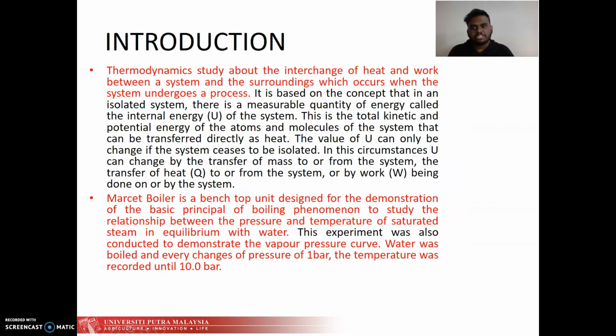For the next part, introduction. Thermodynamics studies the interchange of heat and work between a system and the surroundings, which occurs when the system undergoes a process. The Marcet boiler is a benchtop unit designed for the demonstration of the basic principle of the boiling phenomenon, to study the relationship between the pressure and temperature of saturated steam in equilibrium with water. This experiment was also conducted to demonstrate the vapor pressure curve. Water was boiled and at every change of pressure of 1 bar, the temperature was recorded until 10 bar.